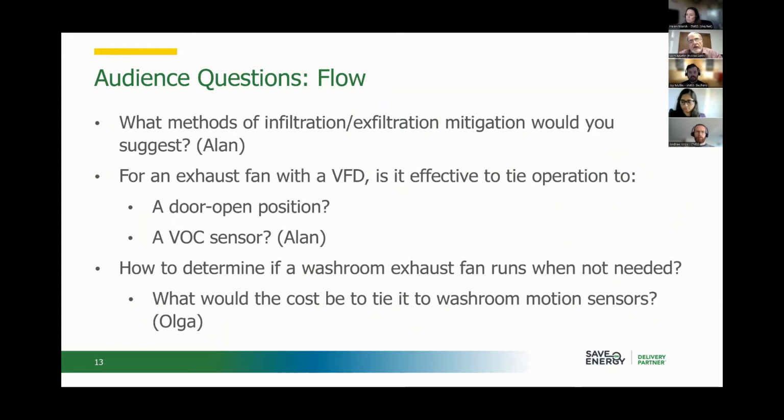So back to Alan's question and how best to answer that. If you're going to try to deal with one of these two, infiltration or exfiltration, I guess you can test. If this is our ductwork from here to here, you test here and you test there, and you see whether or not you're coming up with the same values in order to establish whether or not you've got some infiltration or exfiltration between the two points.